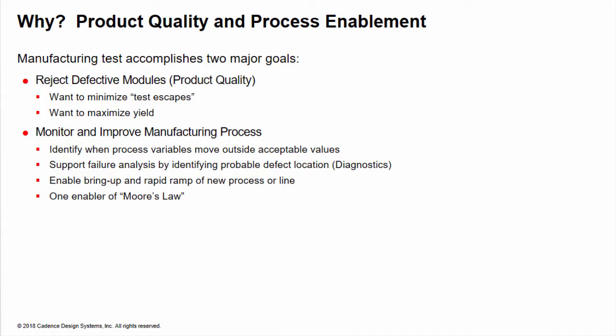First, we do not want to ship defective chips. However, this would not be engineering if there were not a trade-off. So we must balance based on our understanding of customer requirements, minimizing the number of bad chips we ship, called escapes, while also trying to maximize yield. Some kind of defects may not prevent a chip from working functionally. Do we throw it out anyway? Some tests have soft results suggesting that the chip may have problems in the future even though it passes tests now. Do we still ship it? For a wafer, all passing chips except one may be well within tolerance, and one is just barely in. Is it good or bad?